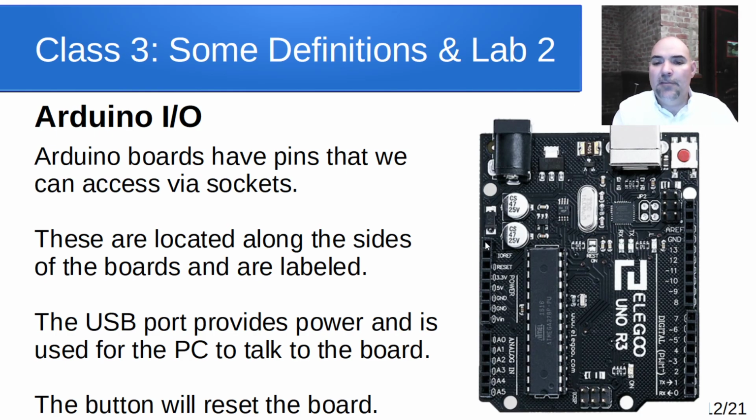So along the sides we have these little sockets that pins can plug into. And those connect to these pins on the actual processor. So this is a microcontroller. It has a microprocessor. It's got I/O. It's got timers. It's got counters. It's got an A to D converter. It's got a whole bunch of peripherals inside of here. It's got memory inside of there. It's got both flash and RAM. It's got EEPROM. All of that is inside of this single computer system on a chip.